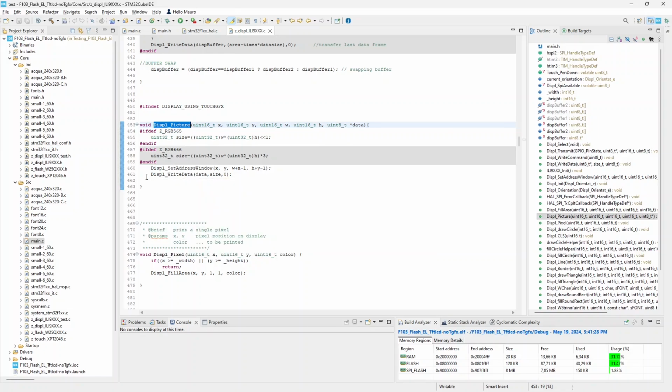We know that some STM32s provide a port making a quad SPI memory transparent to the user, to the program, allowing access to those memories as if they provided direct memory access. But this feature is available only on the higher range of the STM32 family. And we are trying here to have graphics on small displays with the simplest STM32s. So we should implement a second function, handling SPI communication to the external flash and transferring data to the display.